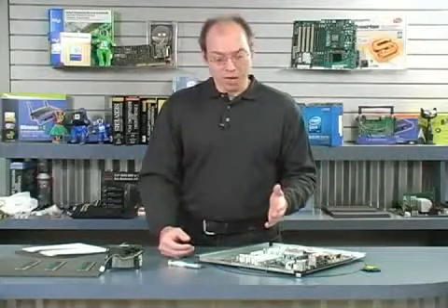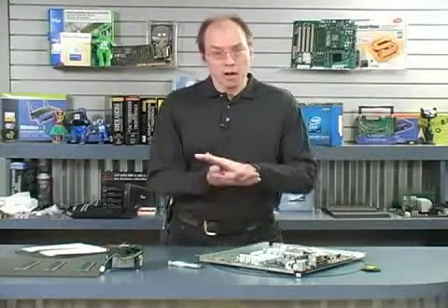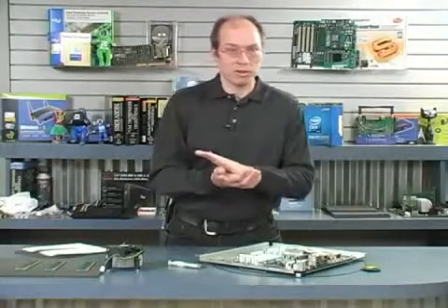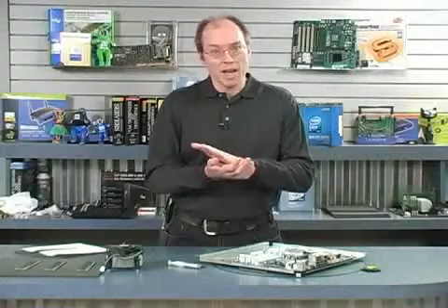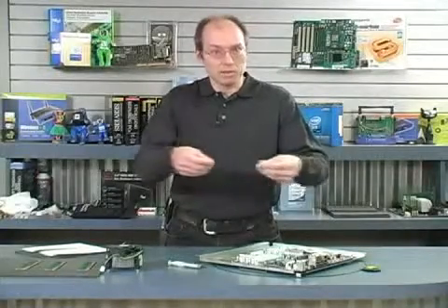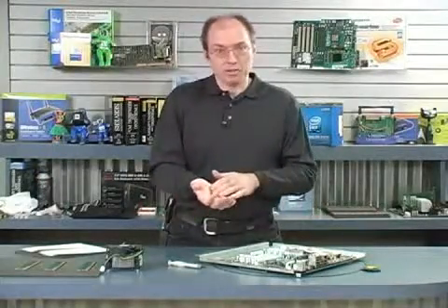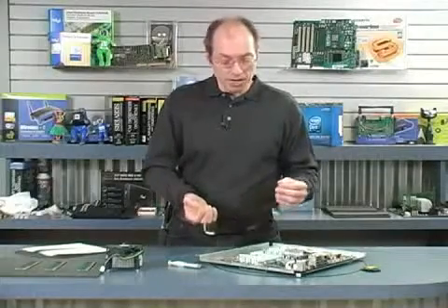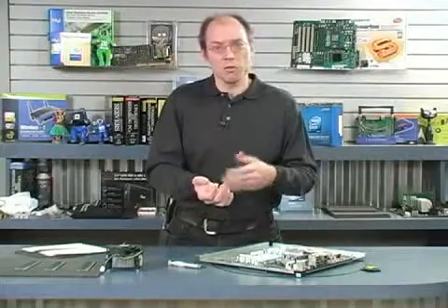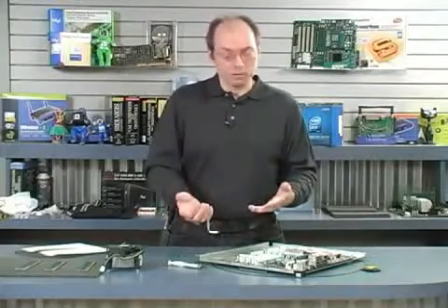Pump out refers to the fact that as the heatsink sits on top of the processor, there is slight movement due to different thermal coefficients of expansion, contraction, and vibration, and eventually this movement pushes the grease out. It extrudes, it oozes out from between. So eventually there's an insufficient amount in there. The other thing that happens is it dries out. The grease usually has a silicone oil to suspend the thermal material, and eventually it can dry out.